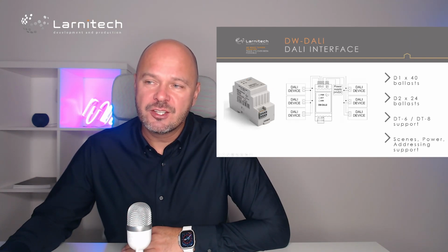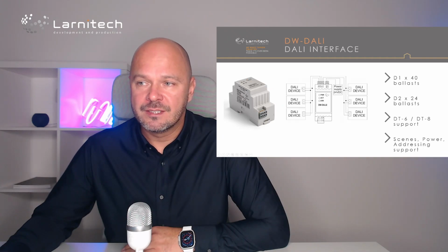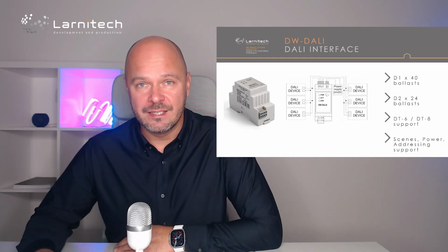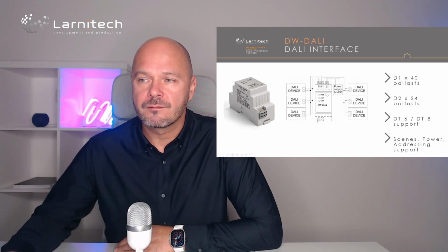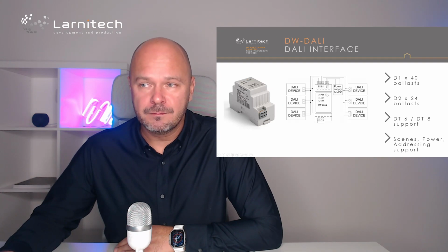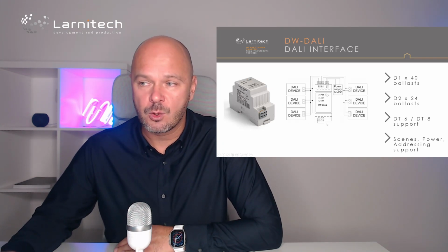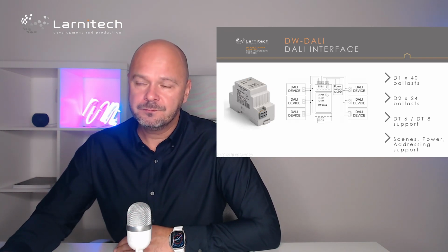DALI stands for Digital Addressable Lighting Interface. DALI devices are usually drivers for LED lighting, mostly. They are addressable, and DALI has 64 addresses for devices, so we can use up to 64 DALI devices with our device. We have two connections in here.